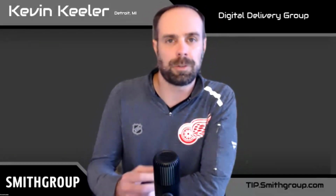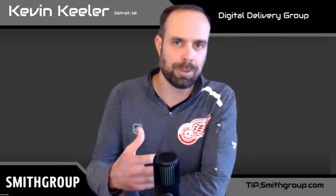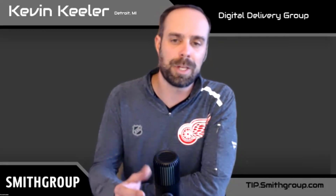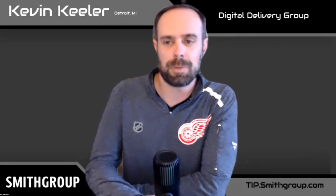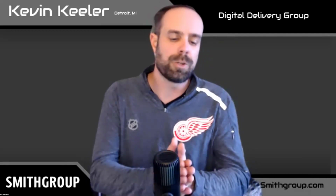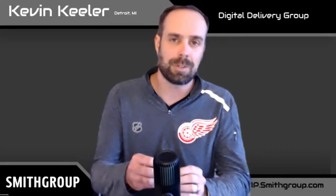Obviously, Revit is our 3D authoring software. There's plenty of ways to view in 3D, but as all of you Revit users know, it can be laggy. You'll get a lot of buffering. So what we employ is other tools that are lightweight 3D viewers, such as Navisworks or, like Dana mentioned, Enscape. The setup we have is our users do day-to-day coordination in Enscape, which is a direct connection to their Revit model.